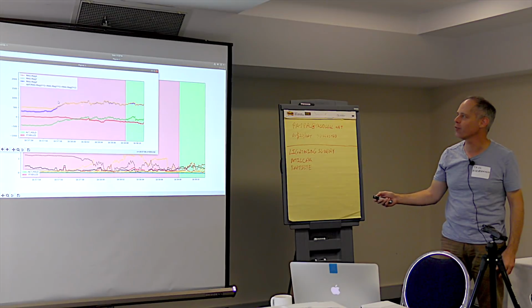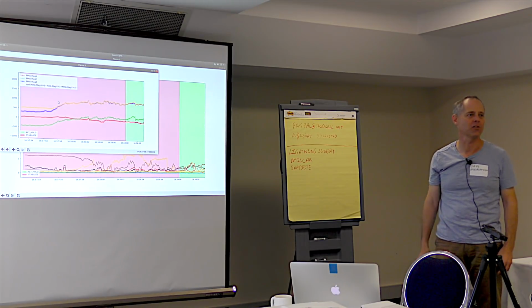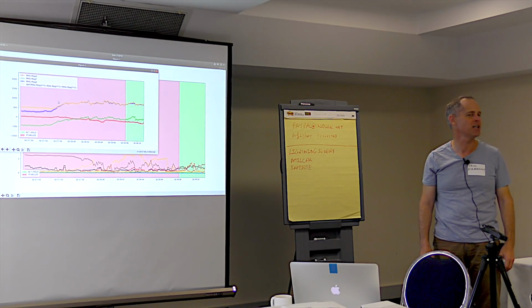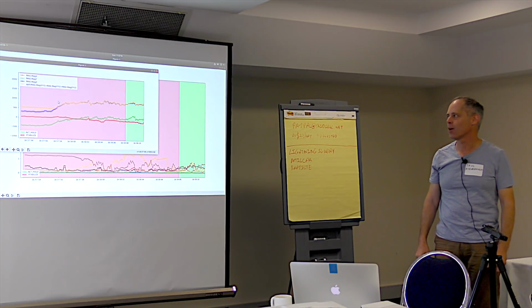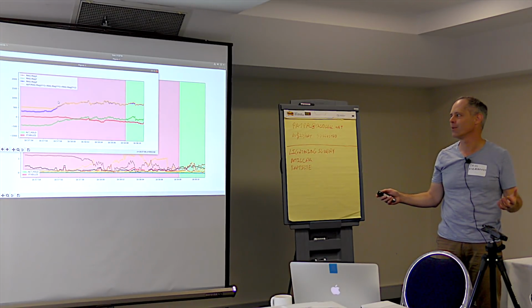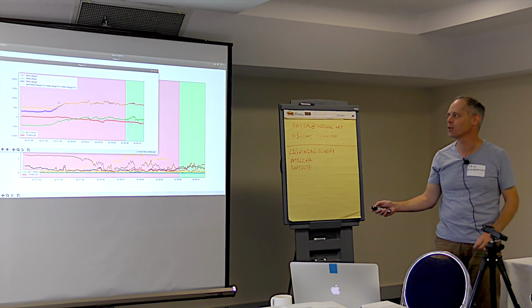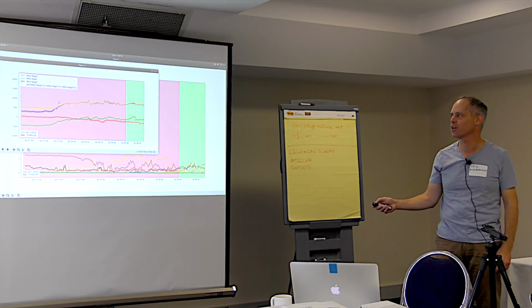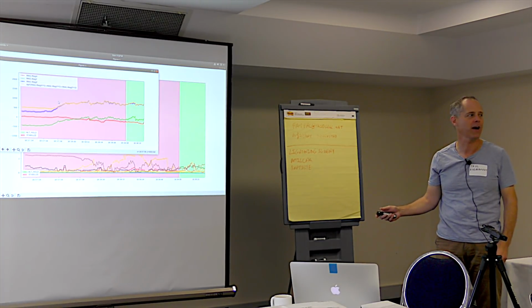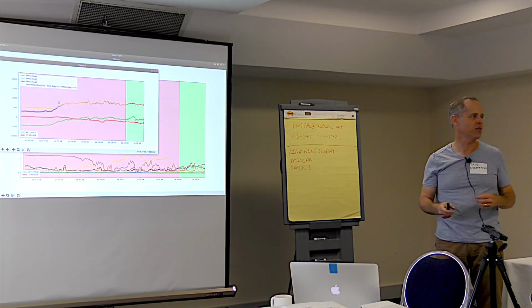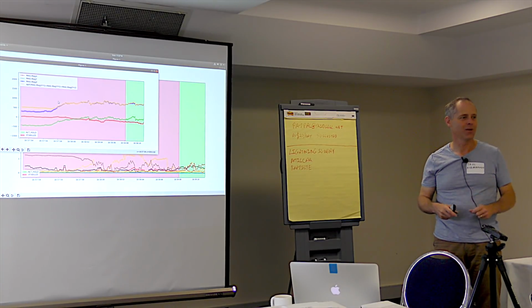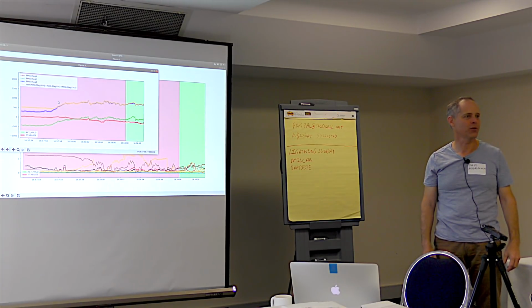It went from just over 500, and in flight it's going up to 1,000. So that's a 100% change in magnetic field strength. So at that point in time, you don't really need to dig too much further into this log. First of all, this is a major problem, and you'd be justified in saying, well, that's what caused your crash. Fix your compass interference, calibrate it, fly your quadcopter again, and it'll be right.